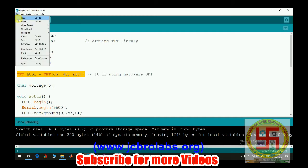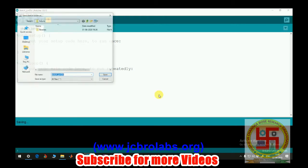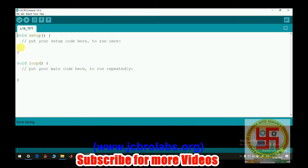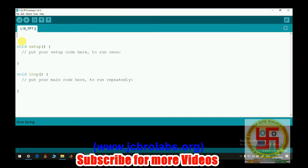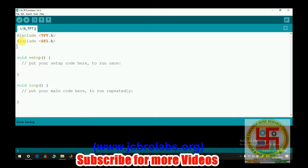First of all, we'll create a new file, and the first thing we'll do is save it. Let's save it on the desktop by the name of lesson 18 underscore TFT. First of all, we'll add header files. The first header file is #include tft.h, and then #include spi.h.